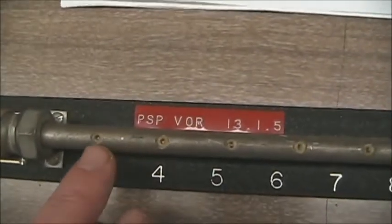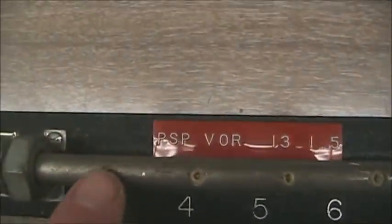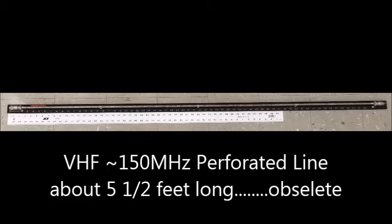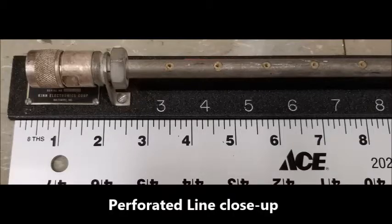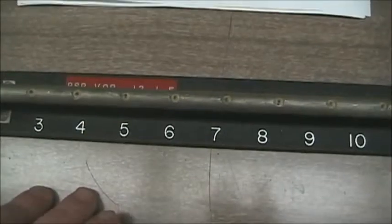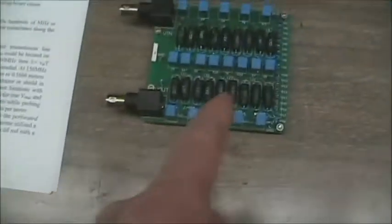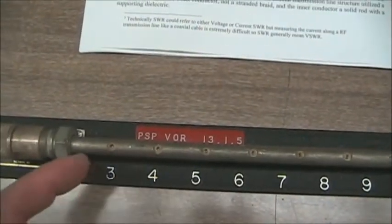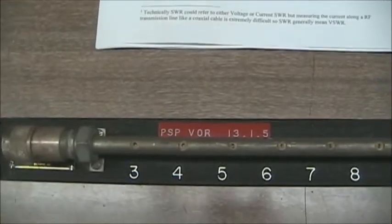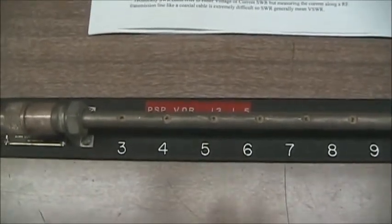And what we mean by perforated is you can see it's a coaxial line. That's an end connector there. And there are holes drilled into the outside conductor. And that would allow us to go and probe these individual points. This, an older unit, has spacing of 1 inch per point, similar to one L or C network there. But this is the distributed line, meaning the L and C are in the transmission line, not as discrete components, but microhenries per meter or per inch or whatever, and capacitance.